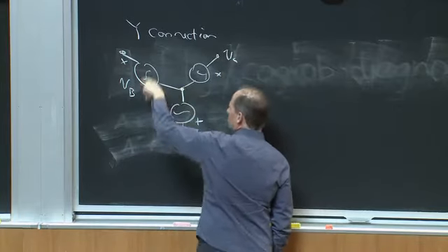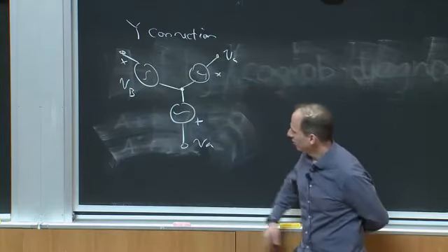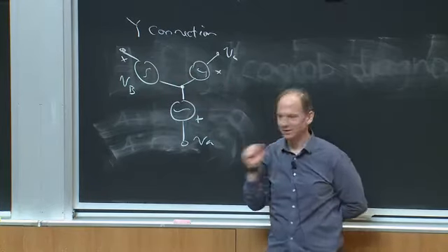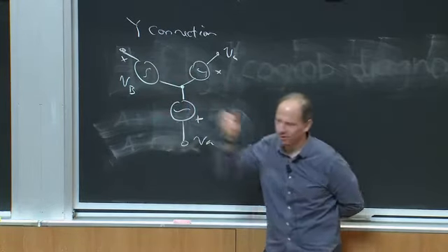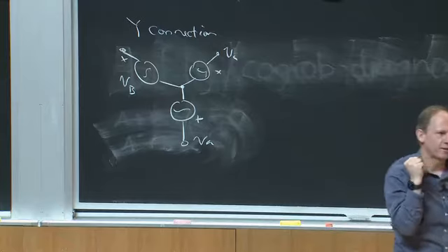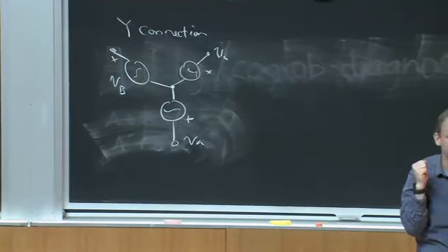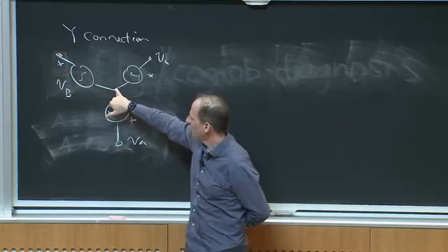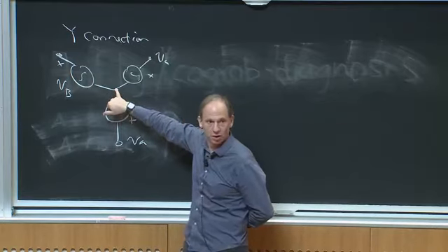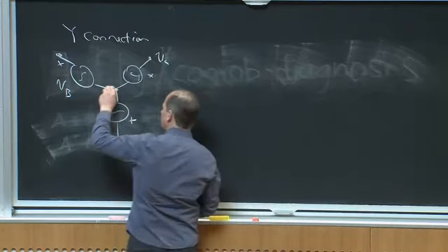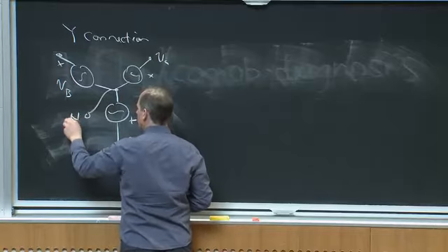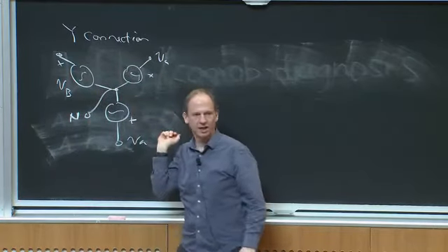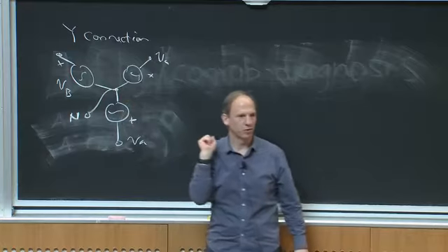Okay, and you notice that for illustrative purposes, sometimes I draw the voltage directions in my schematic in the way they're reflected in their phasor diagram, just to show their relations to one another. That's a convention that people follow. But what I'm doing is connecting one terminal of each source to one node that we're going to call the neutral. That's the neutral point.